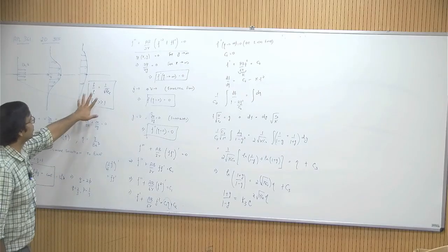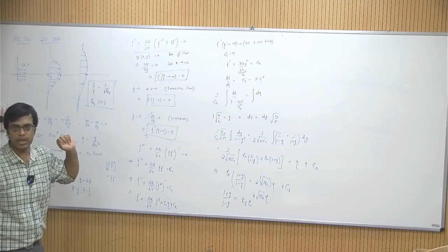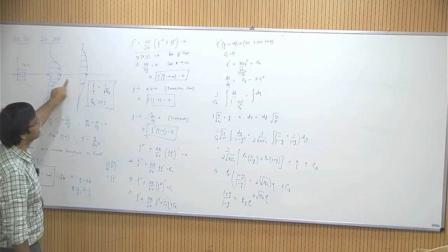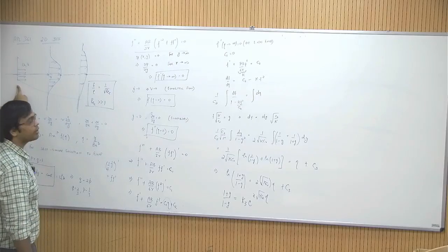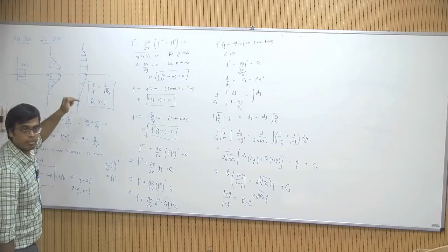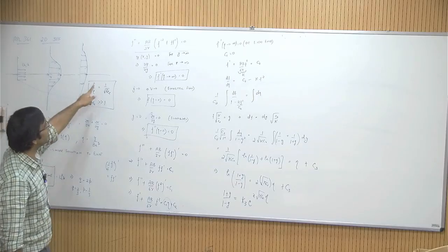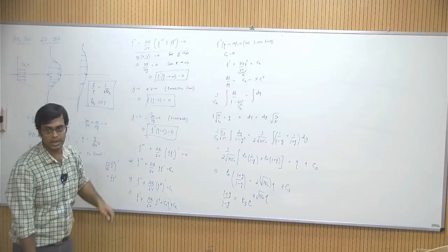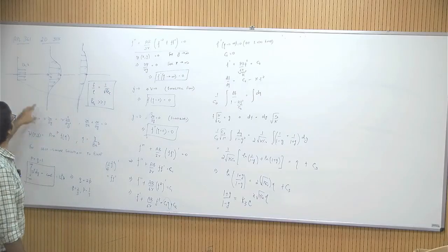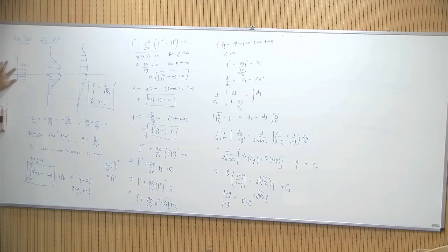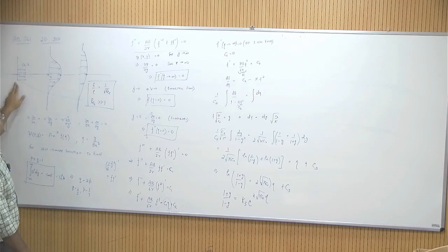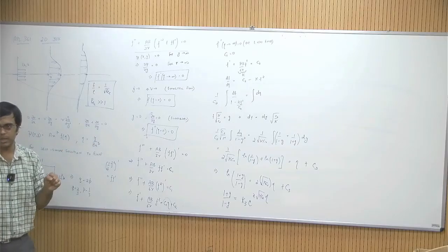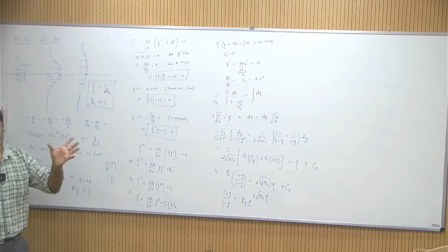So the only meaning of these two conditions together is that we are zooming in far away from the inlet of the jet, or if you want to think of it as an outlet, far away from this jet where it is emanating, and not so far away from the center line. Okay, if this height is h, usually in 2D planar jets, 50 h away from this point, you can see self similarity experimentally, but you have to be 50 times that h.